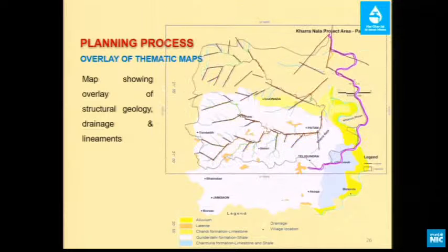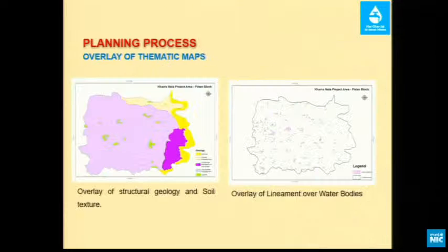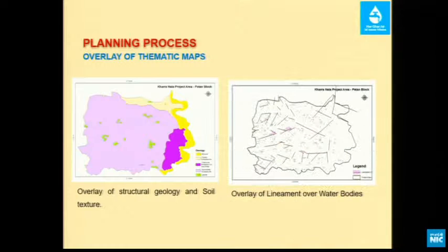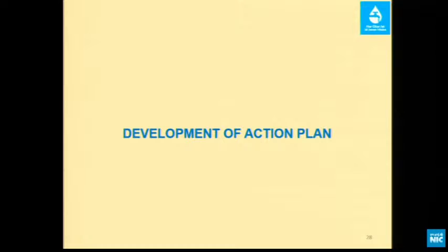This is the detailed geology. So again, I am putting an overlay, see here. With that overlay, geology has now been overlaid because I know what the geology is. In most parts of the area it is shale, which is not rechargeable, but my soil condition and soil structure are excellent, 48 lineaments are there, and 4 or 5 faults are there. So this is a rechargeable area. I have proved it.